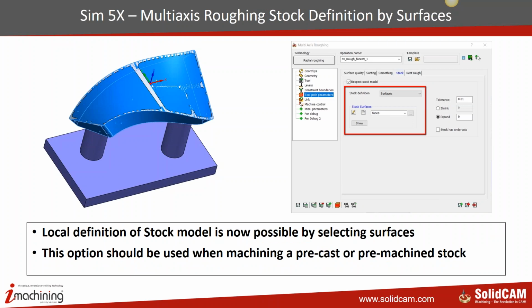Multi-axis roughing: we now support stock that you can define locally. Many a time when you are using multi-axis roughing, you will find that it starts calculating the previous stock, and then goes into all those areas where you think it should not have gone. Then it becomes very difficult to control. To avoid all those things, we can now define local stocks. That means stock only for that operation, and this can be defined by simple surfaces.